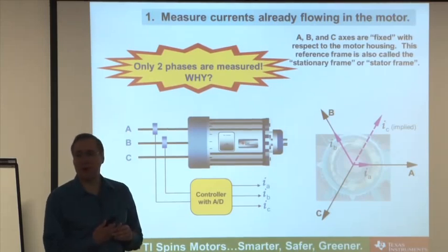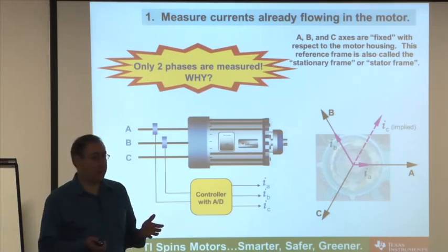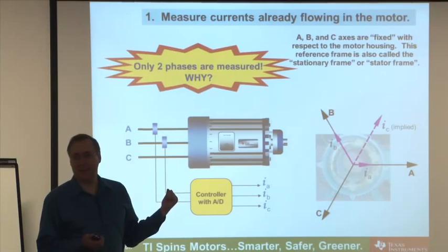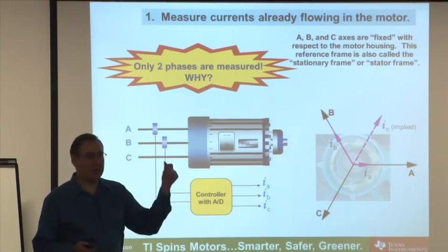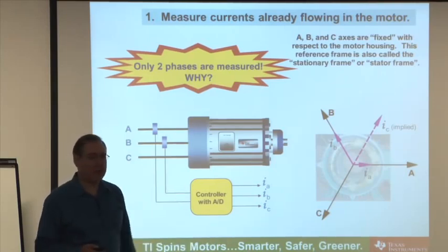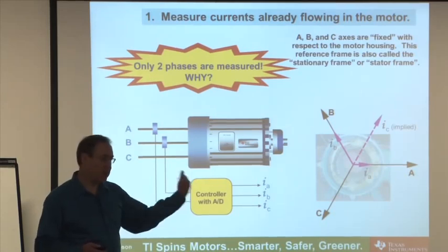Now sometimes in industrial controls, you do see that they have 3 current sensors. Any guesses as to why? A lot of industrial motor drives will have 3 current sensors. Yes, both of you are right. If I have a winding to frame short, guess what? That law is broken, and then I can use my third current sensor to say, whoops, we are not seeing the right current. Therefore, you trip the fault light, bring the drive down to a safe state, and then flag the technician to say, go replace the motor.